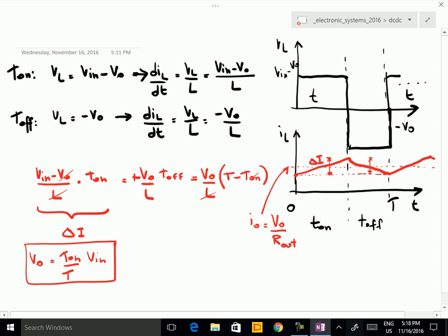This is the, let's say, extremely simple part. It's easy to understand what's happening here. If we change the duty cycle, we change T on with respect to T, and then we can change V. If, for example, the battery discharges, then the voltage of the battery is reduced, because this is what happens during the discharge of a battery.